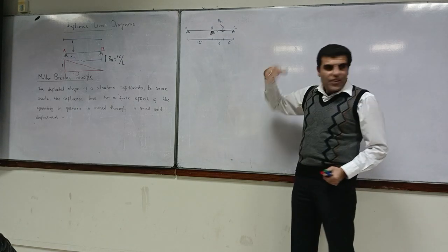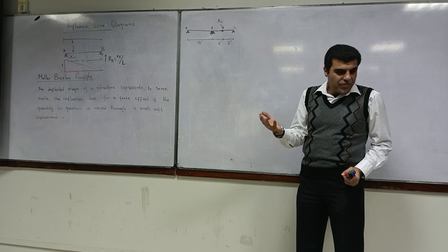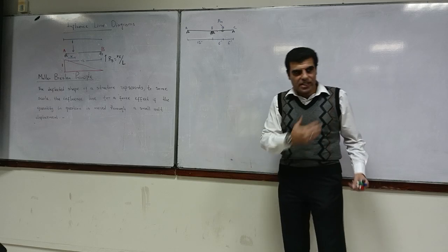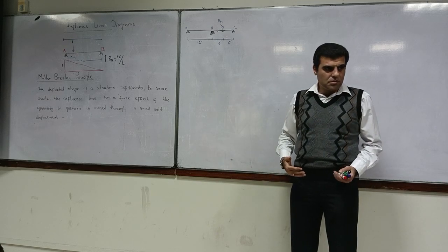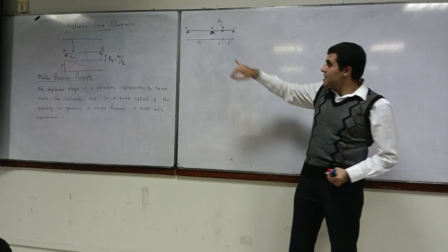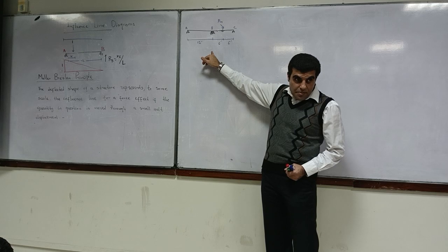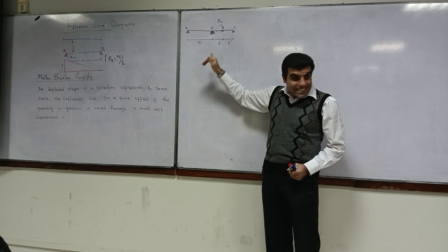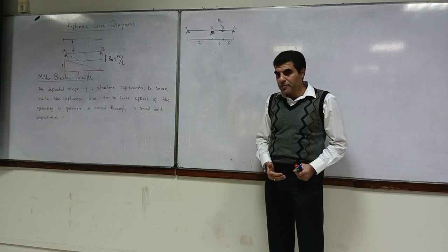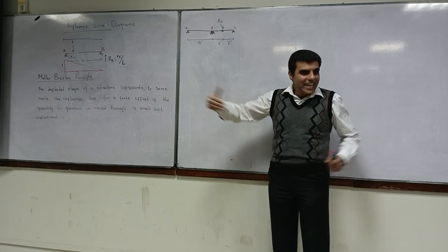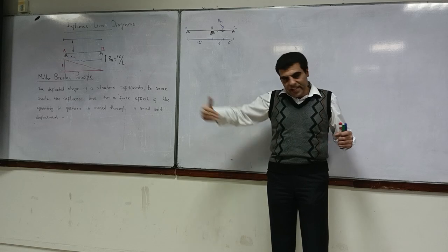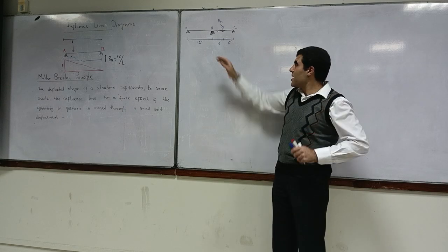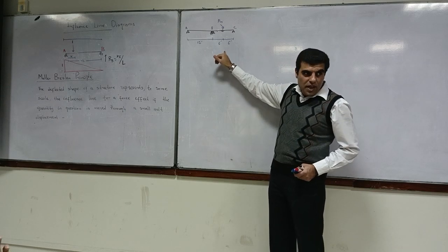I'm saying that we are not considering the horizontal, so it doesn't matter to us. We are not trying to find out the horizontal load. You don't have an influence line with load running horizontally. But this is determinate for vertical load. This structure is determinate for vertical load. It is not determinate for a horizontal load. Horizontally, you can have, for example, some waves generating and moving, but we are not taking that. We're just taking vertical load.